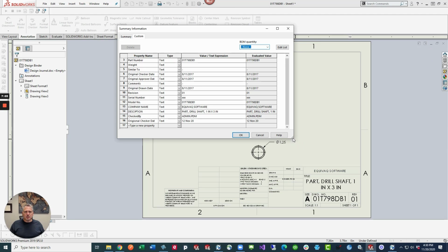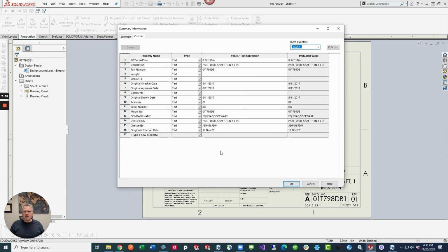In the custom properties right now, you'll notice that we don't have anything that shows watermark because that property hasn't been communicated through to the data card on any of our files yet. So we have to put it in here manually the first time, but then every time the file gets updated inside the workflow, that will get reset and taken care of. So we're going to call this one watermark, call this not for production. And this will match our values on the data card.